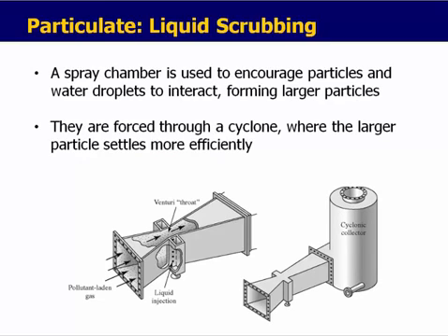And so what happens here is your gas comes into a venturi valve. What happens through this venturi valve is that gas is pushed through a small diameter, which increases the velocity as it goes into the next step of this. It creates that high velocity. While that's occurring, we're also going to inject liquid.